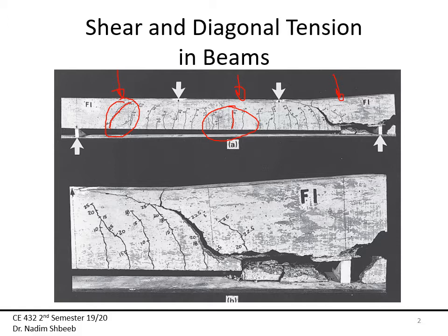And that was one of the emphases that we had during our designs. Now, shear, on the other hand, usually a shear failure is quite sudden. So there are no warnings. It will just happen, as it did with this beam right here. So this one failed immediately at the reaction at this high shear point.